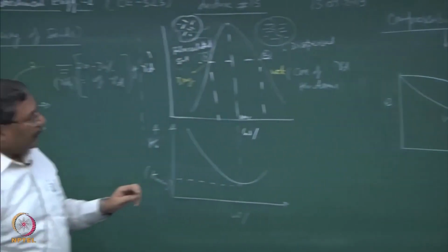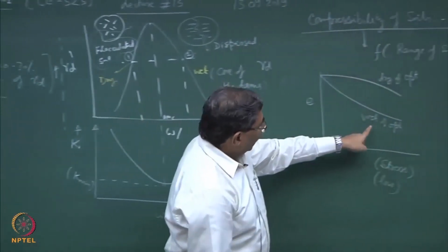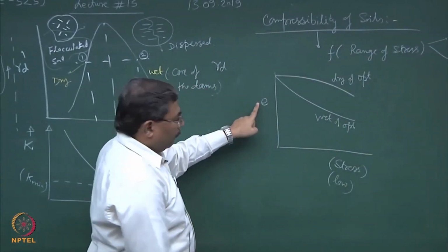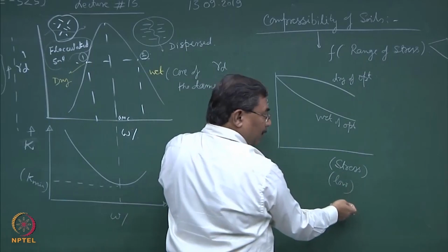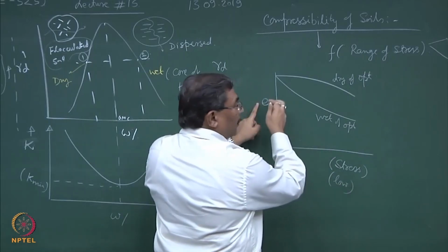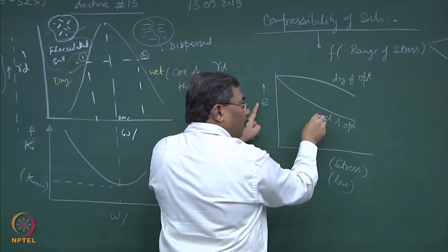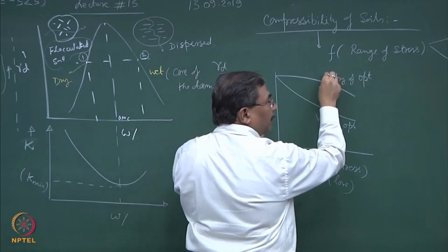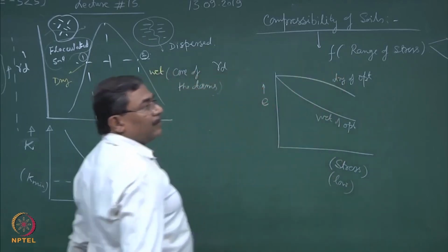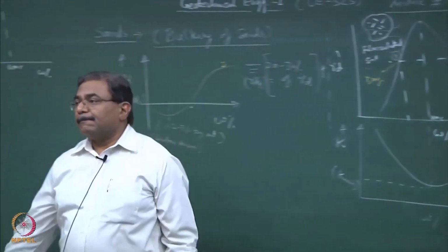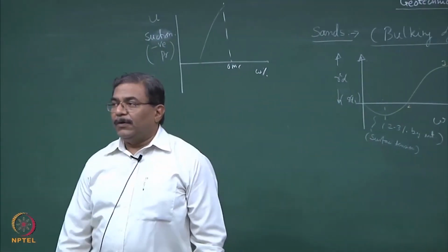What I am trying to show here is wet of optimum for low stresses in the kilopascal range, the volumetric deformations are going to be more as compared to dry of optimum. Clear? Fine.